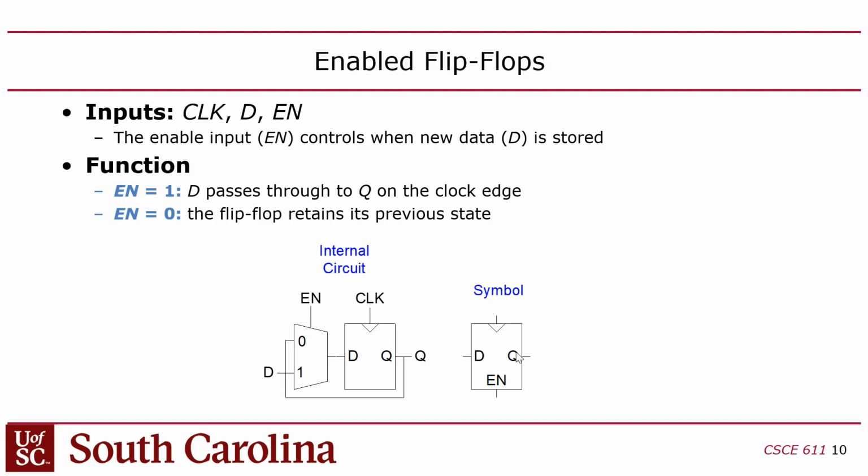Yes, this is for your IO2 out. So you have one register in there, at least one register. Is there another one? I think there's just one. So there's a register that drives the hex displays. The only time that register should be enabled is when the CSRRW instruction is in the execute stage and the immediate field is 2. That's the only time that register should be enabled.